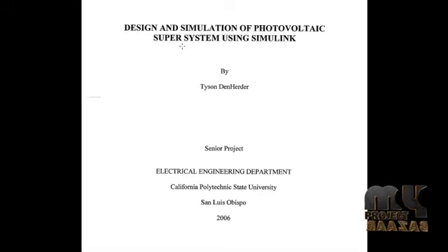We design and simulate the photovoltaic super system using Simulink. The Simulink model consists of PV array, maximum power point tracker (MPPT), battery charger, DC to DC converter, switch control and load. We simulate the photovoltaic system under two different scenarios, sunny and cloudy conditions, with constant load. To convert the irradiance data and temperature into voltage and current, we use a two level S function. The simulation is very useful for determining what types of PV modules, batteries and loads can be successfully combined.